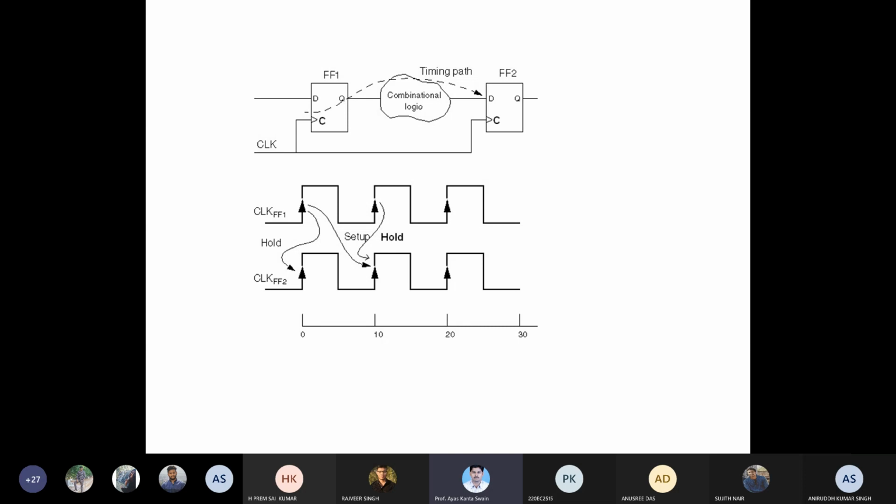Most of the structure, input and output of these solutions are the same. They take the same timing characteristics as design constraints, your RTL-level gate-level netlist after synthesis, and the vendor-specific library and its parameters. Then they find the setup violation in each timing path. The tool can do it for you very easily.